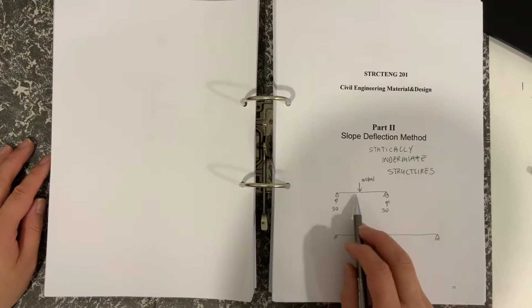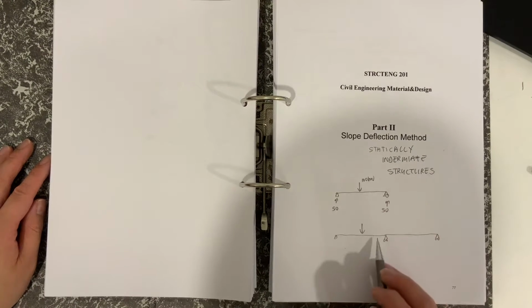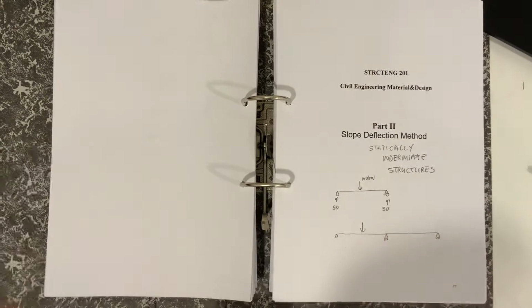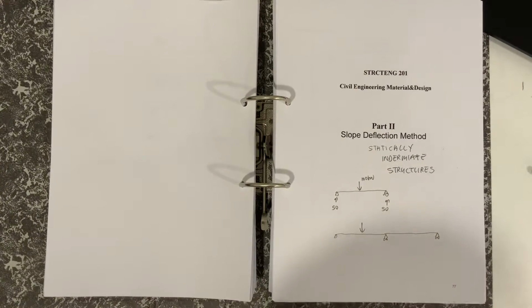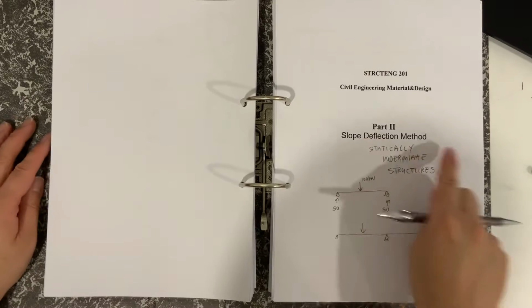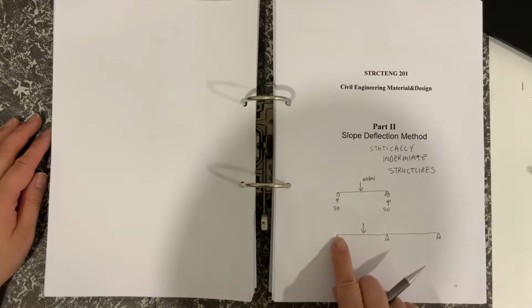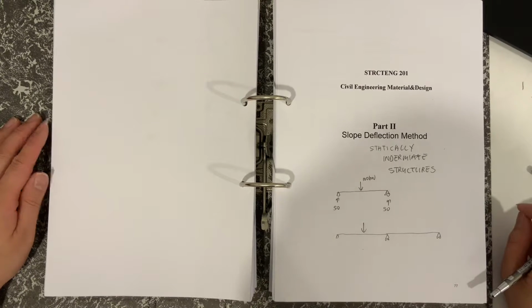So we can see here a statically determinate structure where you can work out the forces just by inspection, and by adding another span, or perhaps by making that end into a fixed one instead, you've suddenly got a statically indeterminate structure. So the slope deflection method was probably one of the earliest well-used methods for calculating such statically indeterminate structures. And it was later replaced by another method which is called moment distribution, which Gary Raftery will be teaching you in the third year.